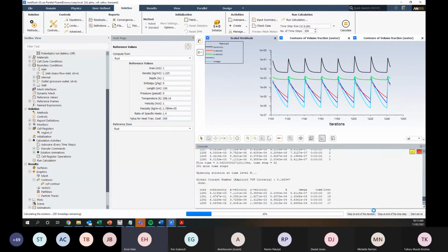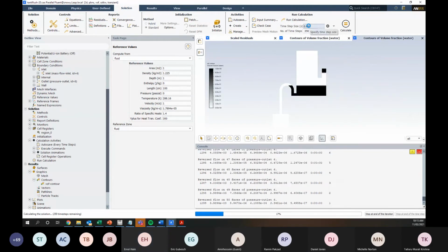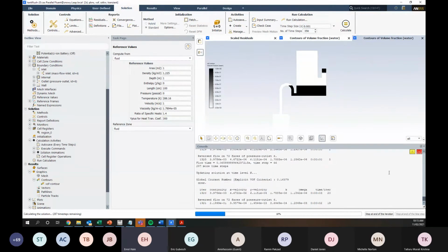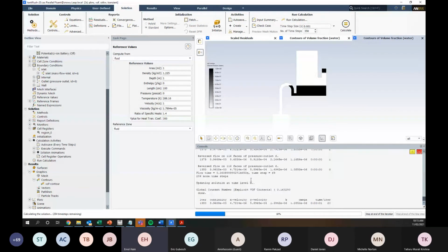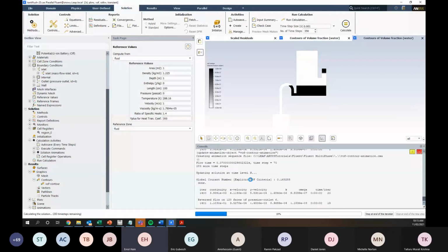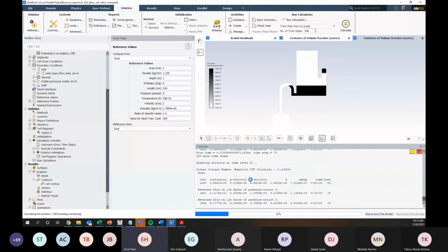Well, we're not really getting great convergence behavior here. Let's try and get this running more smoothly. Yeah, once again, a very case-specific problem. K omega SST is still really applicable for most applications in multi-phase. But depending on the application, if you have high turbulence, you need to understand that turbulence.